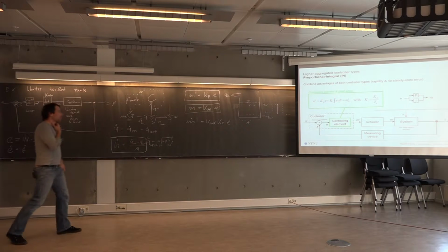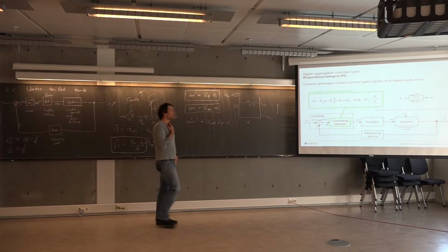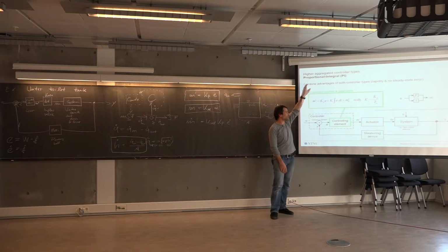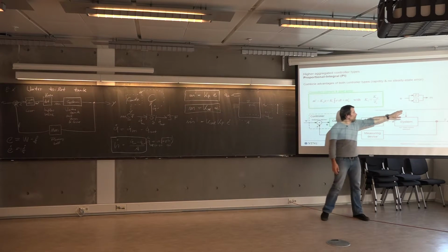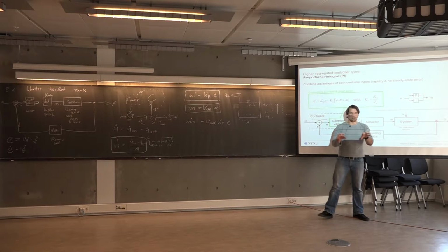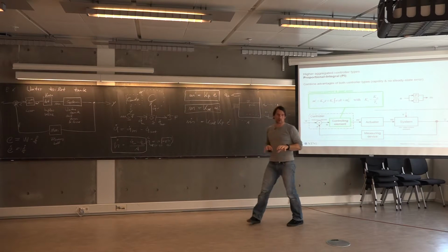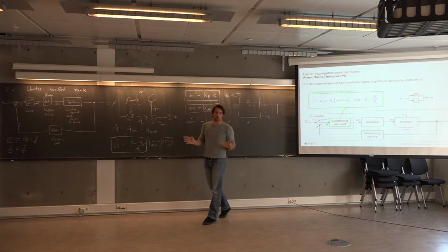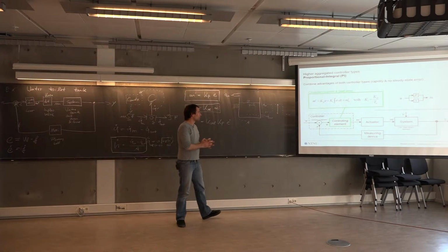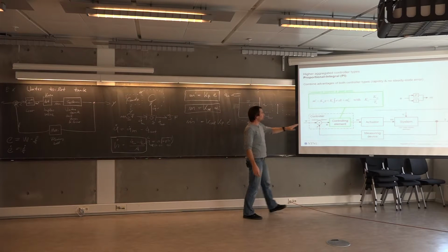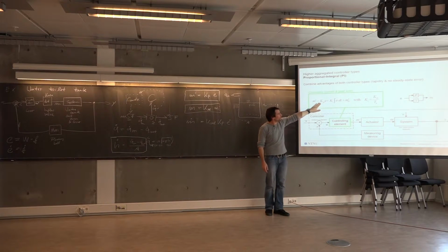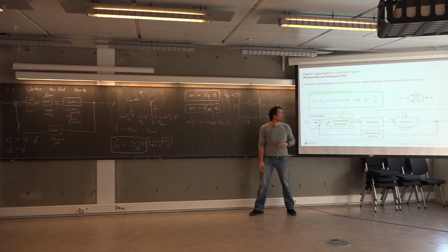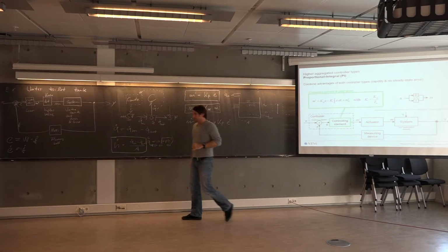If we, for instance, combine this integral control type with the proportional control that we know, meaning that we put these two controlling concepts in parallel, and by doing so just basically combine the equations, we get this constitutive equation, which is the P part and the I part, the integral part.